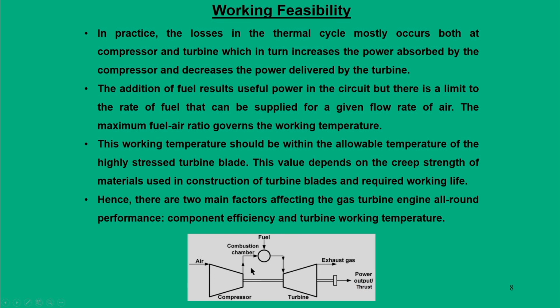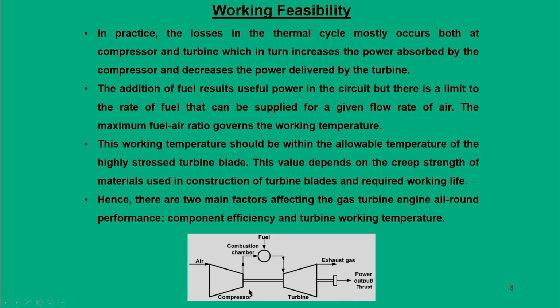The other limiting case is how much compression we can achieve through a compressor. In a realistic sense, although it is very easy to say we can achieve a pressure ratio of 30, 40, 50, 100 or so, handling those high pressure ratios becomes a critical factor. So, the limiting case would be that the components, turbine or compressor, as far as pressure and temperature are concerned, should all run at the best possible efficiency. That is what we call component efficiency.